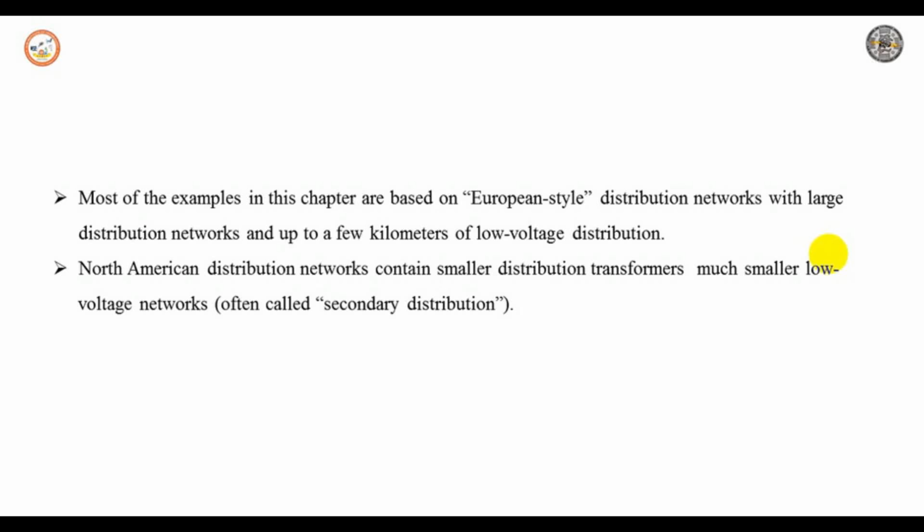So consider one example, where voltage fluctuation is caused by an arc furnace, one of the most common causes of voltage fluctuation in a transmission and distribution system. The flickering signal is defined by its RMS magnitude, which is expressed as a percentage of the fundamental value. If voltage flicker is measured with respect to the sensitivity of the human eye, typically the magnitude will be 0.5%. This can result in a perceptible lamp flicker if the frequencies are in the range of 6 to 8 Hertz.